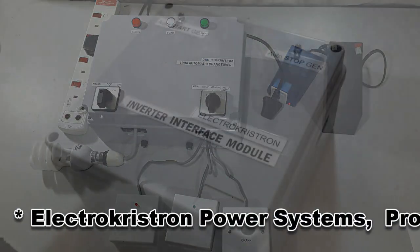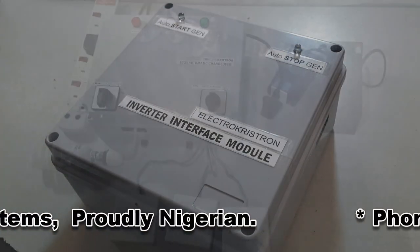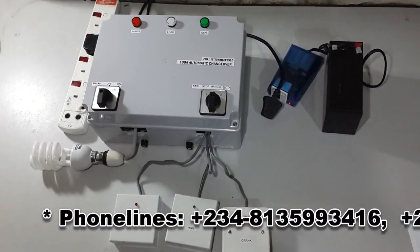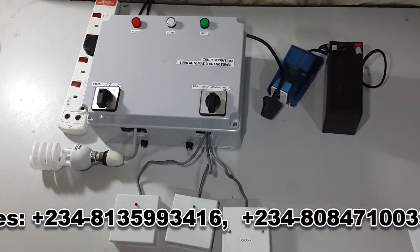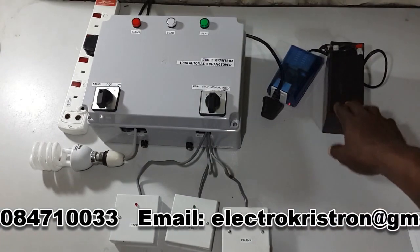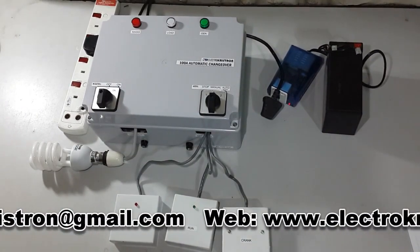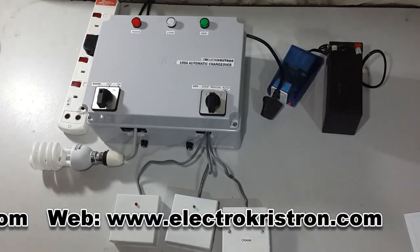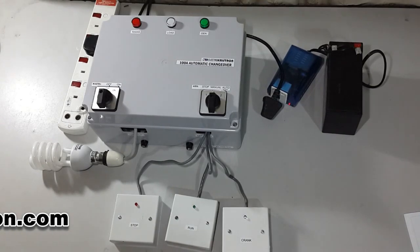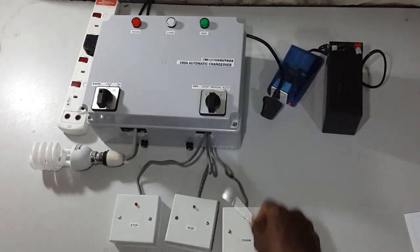But with the help of the inverter interface module, the automatic changeover's AutoStart command is placed on hold while it monitors the inverter batteries to see whether they are good enough to run, until such a time when they need to be recharged, and the command will then be given to start the generator.